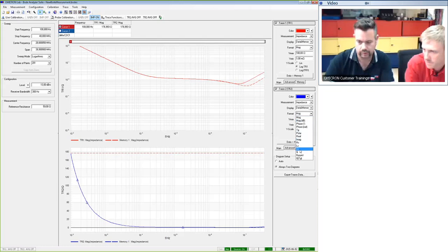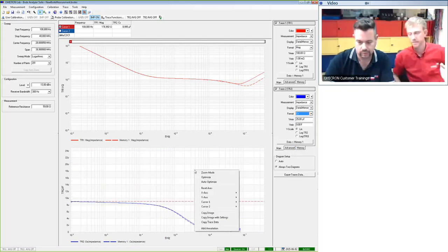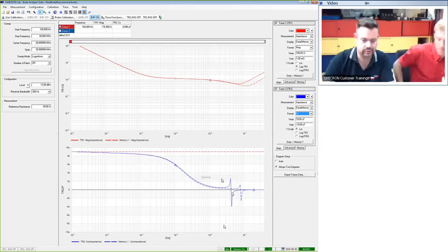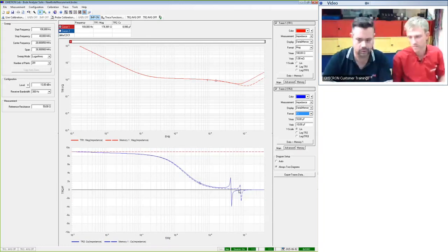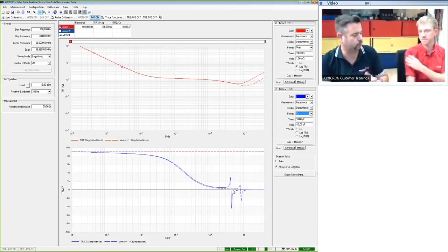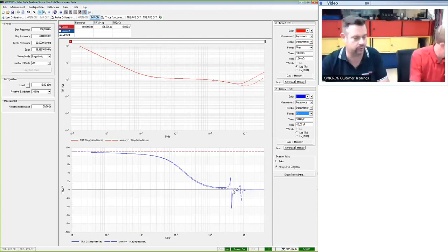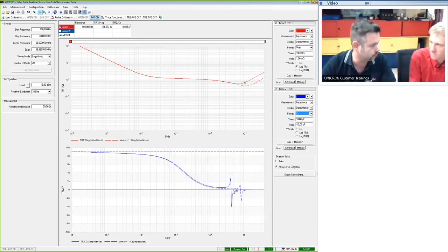I want CS. So here you can see it. Now you can see how the resonance frequency has shifted, just due to the fact that we have 5 millimeters more of leads. So if you, for example, plan to put in this capacitor due to space requirements lying, you will have longer leads, and therefore you already have a different performance, different resonance frequency. But even more interesting is the different ESR and different behavior for different capacitors.